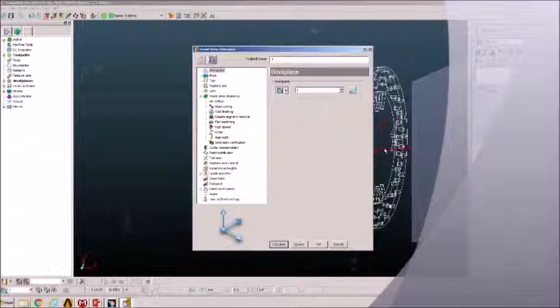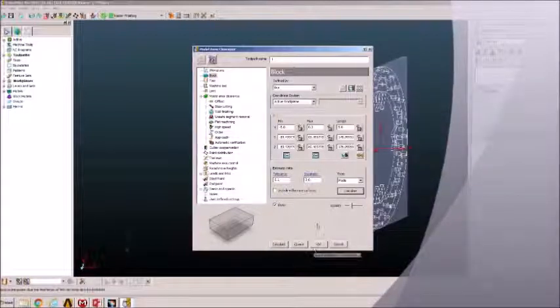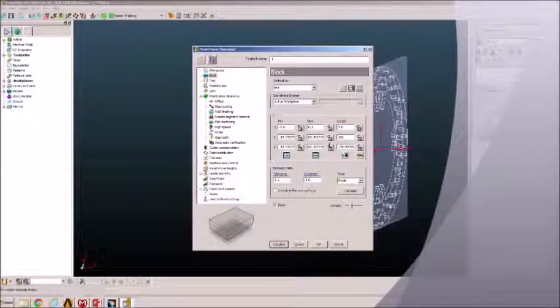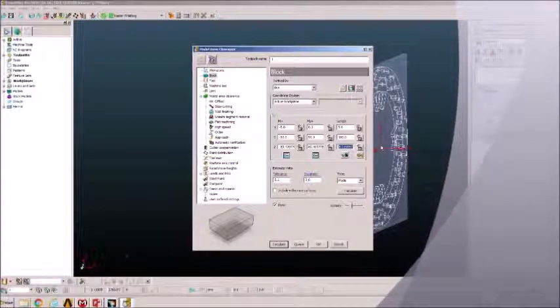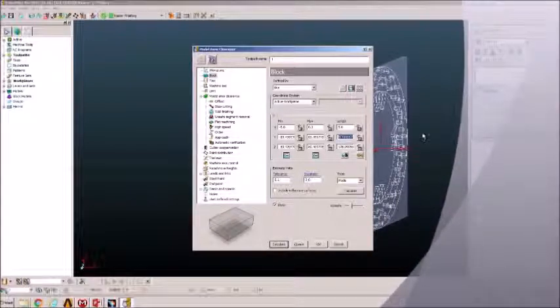An axis system was then placed in the centre of this newly created block. The calculate button was used again to place a disc into the block. However, as the disc is a circle, it had overhangs on each of the edges. To make the disc a perfect circle when it is machined, we had to increase the block size to 185 by 185 millimeters.